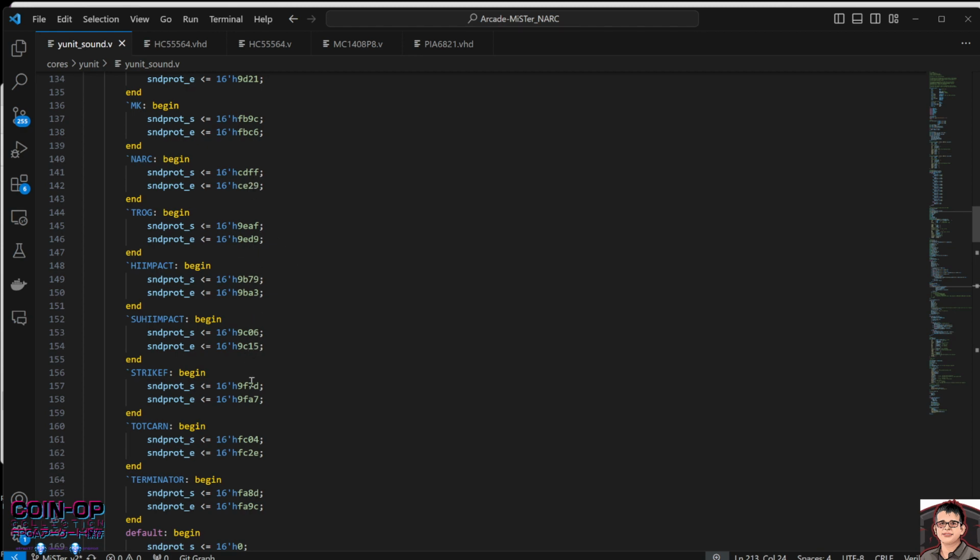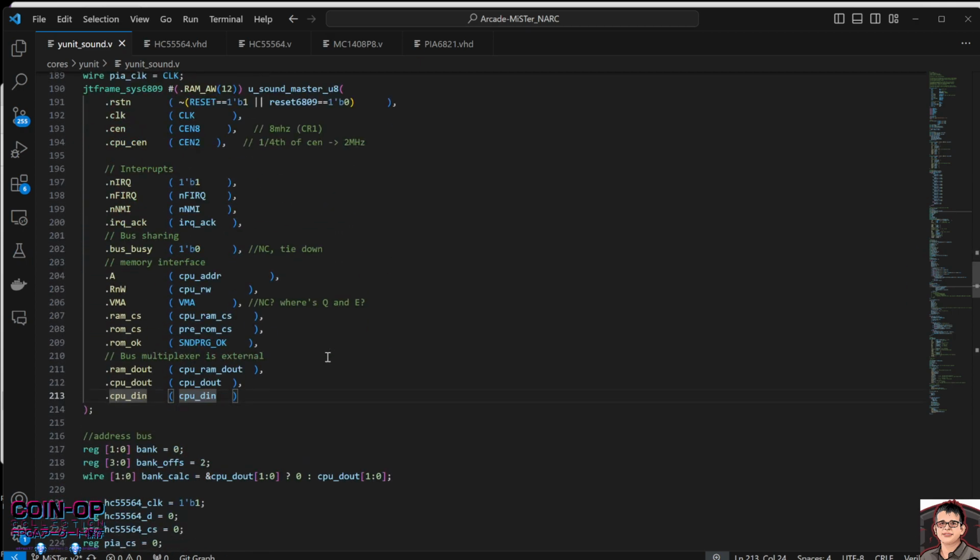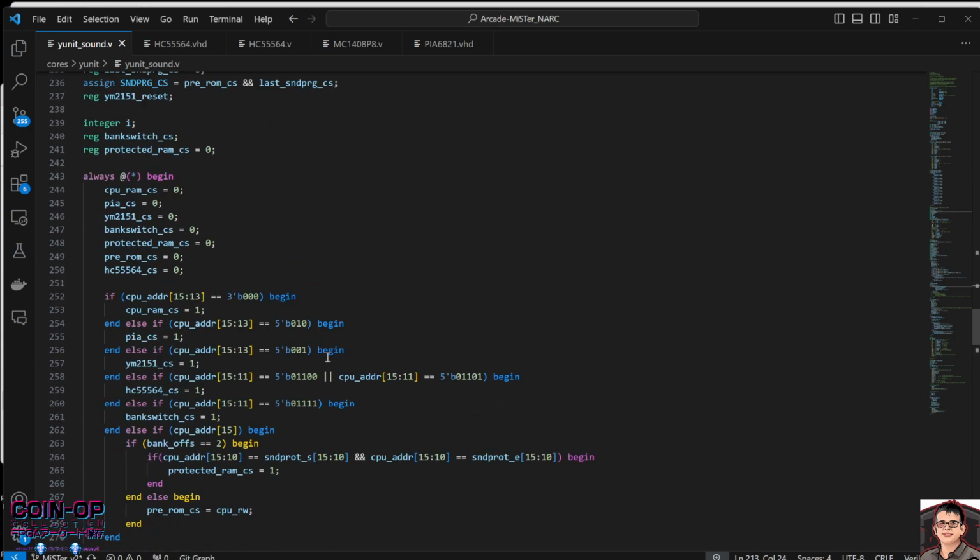It's not generic enough to do that. And plus, it's a range. It's in between this and this. Since these are two seemingly random addresses, it's not really going to work out. So what I would do there is do a greater than or equal to and less than or equal to for that range. But if I can do a mask, I prefer to do a mask because it's easier on timing. It just takes fewer resources, from a logical element perspective, to do this compare than to check whether a range is bigger or smaller.